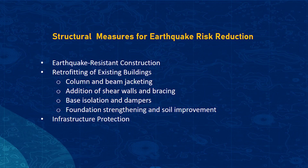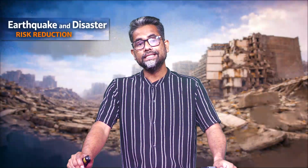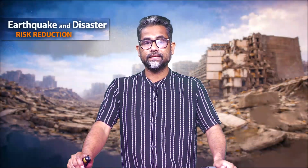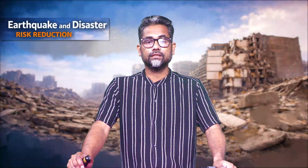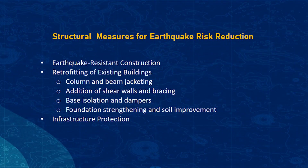Retrofitting of existing buildings. Older, non-engineered and vulnerable structures, especially schools, hospitals, heritage buildings, and multi-story residential blocks, are strengthened using techniques such as column and beam jacketing, addition of shear walls and bracing, base isolation and dampers, foundation strengthening and soil improvement.